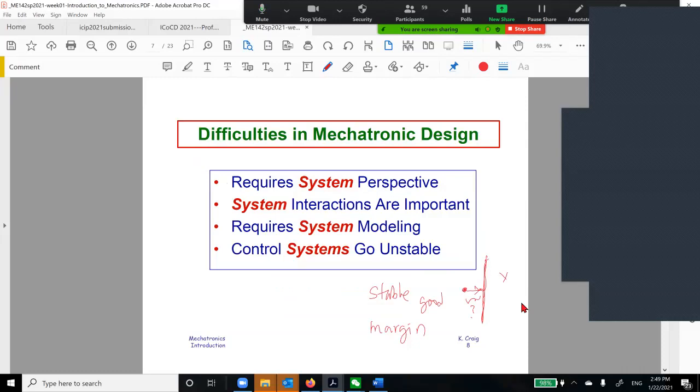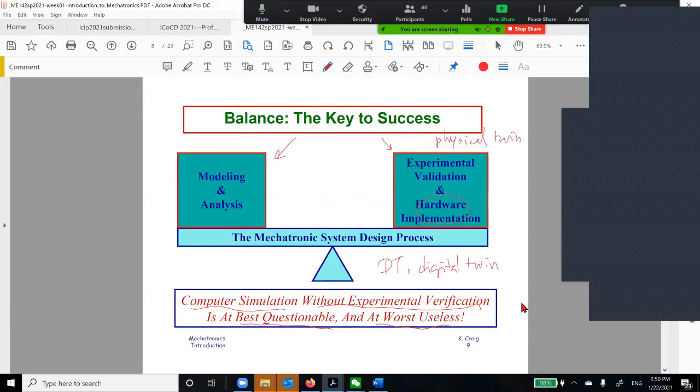We talked about the system, and when you do closed loop, a stable system originally can go unstable if we do not control it properly. So for stability, you also need to ask the question, how stable? How far away is it from unstable status?